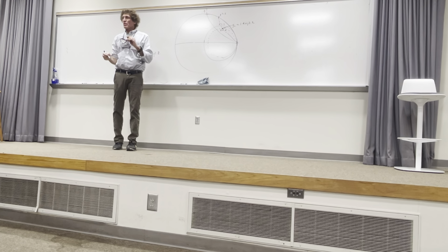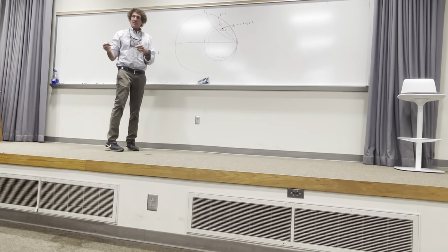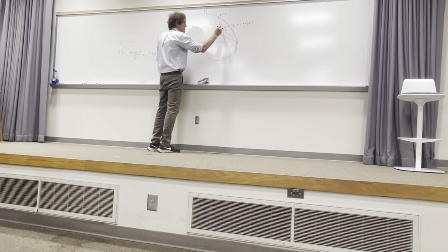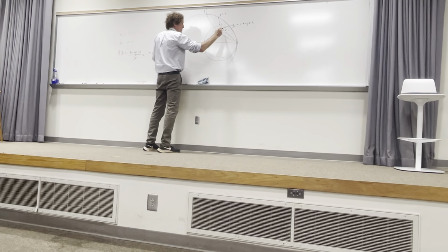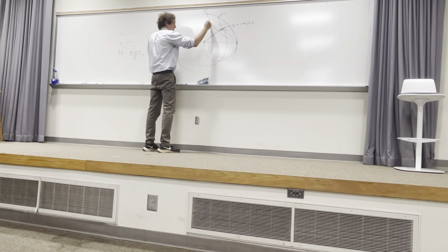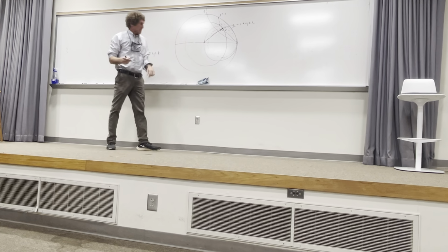All right, now I hope you brought your compass and straight edge. So the next point, remember, it's going to be a shunt stub connection, so we're going to go right into the admittance domain. Follow me, class? Everybody with me? Admittance. So if you have your compass, just take it out to this point from the center of the circle, and then draw a circle of constant radius here, which is a constant magnitude reflection coefficient. It'll go like this, as such. Just draw that out.